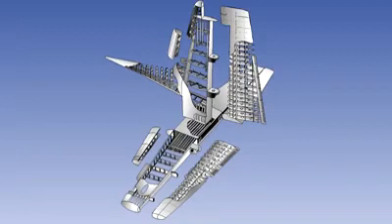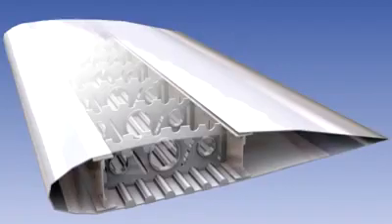Structurally, the tail unit components are generally smaller versions of the wings, in that they use spars, ribs, stringers, and skin in their construction. On some aircraft, they may also contain sealed compartments for fuel storage. They are also constructed of the same basic materials as the wings. Usually, aluminium alloys are used, with composites filled with honeycomb structures, or high-density expanding foam, sometimes being used for control surfaces to provide greater stiffness at low weight.